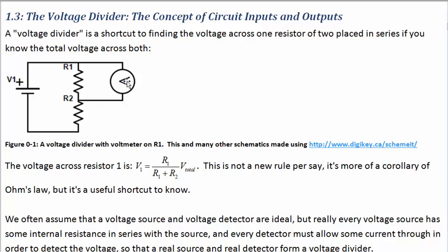Now, why is that true? Because this is a voltage meter, a voltmeter, and no current goes through that. So you can pretend that's not even there. Just don't worry about this little guy. All the current that comes out through there goes through these 2 resistors. Okay, so that means the two resistors form a voltage divider in that they divide the total voltage drop provided by this battery between them.